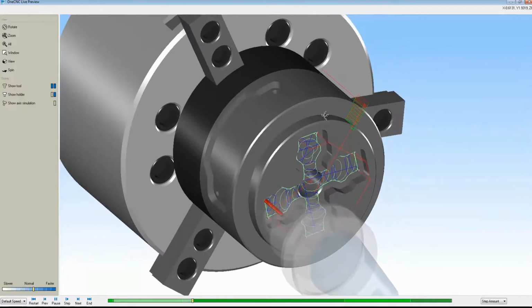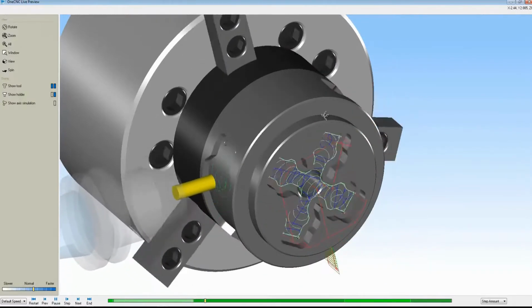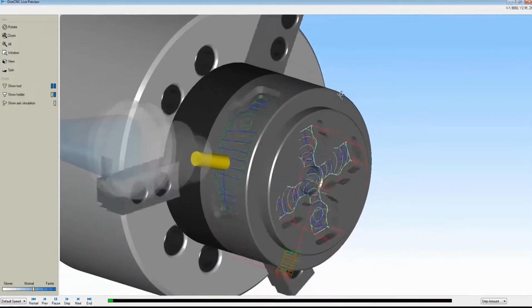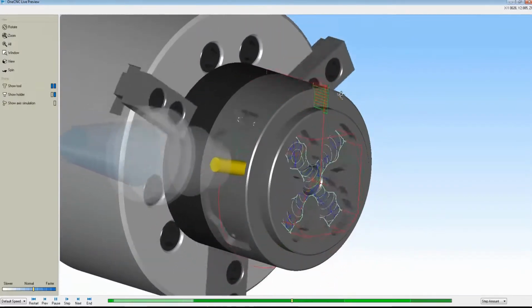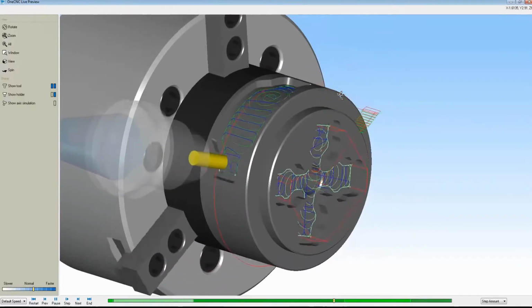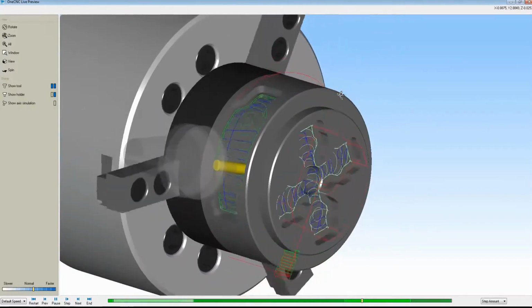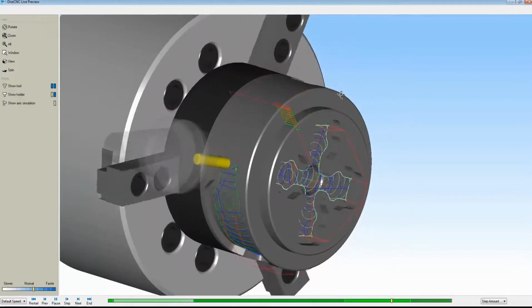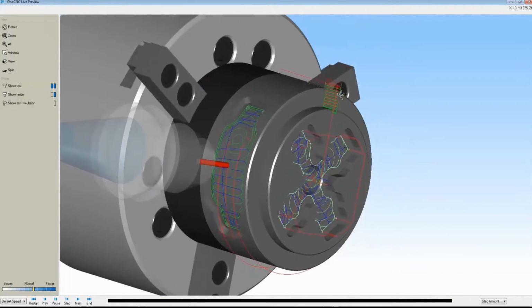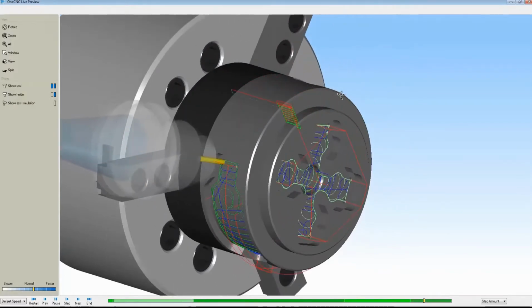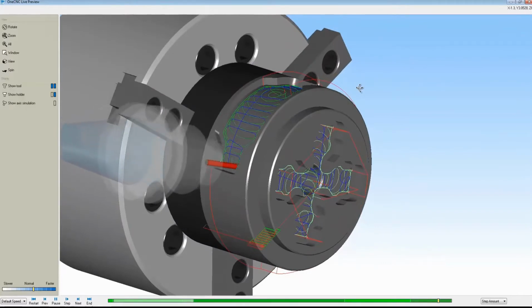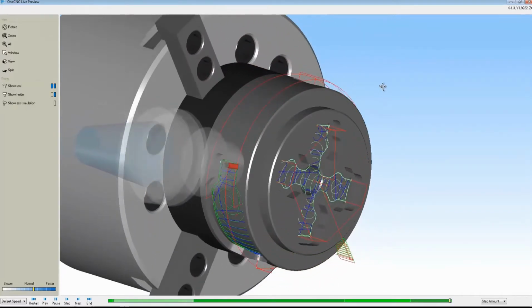Now we'll drill that center hole and then use a chamfer tool to chamfer the hole. Now we've switched tools to a radial end mill, and we're performing some high-speed machining as well on those pockets. We'll switch tools and then we'll perform a finish cut on both pockets. And then lastly, we'll switch to a drill and then drill those holes along those radial pockets. Very, very nice and efficient. So there's a quick overview of the C-axis axial and radial machining within Preview.